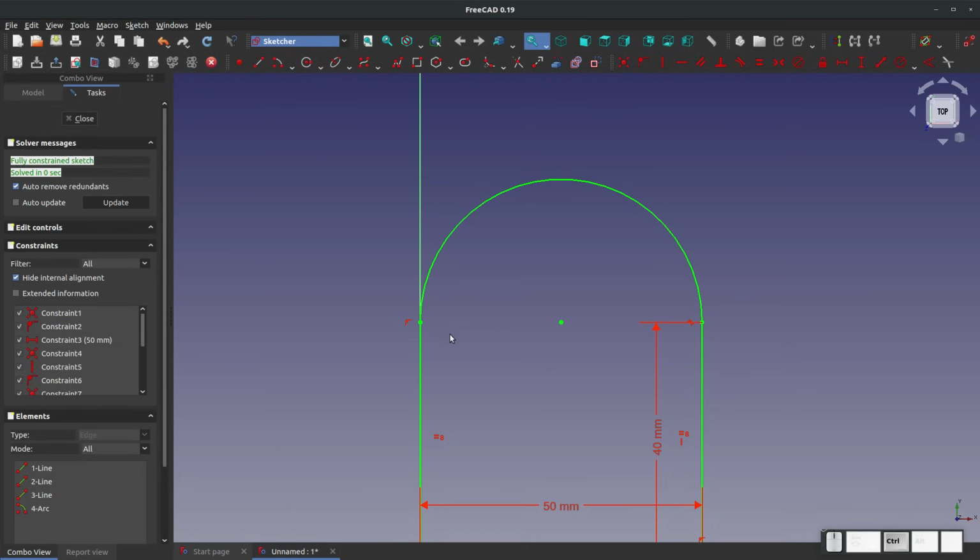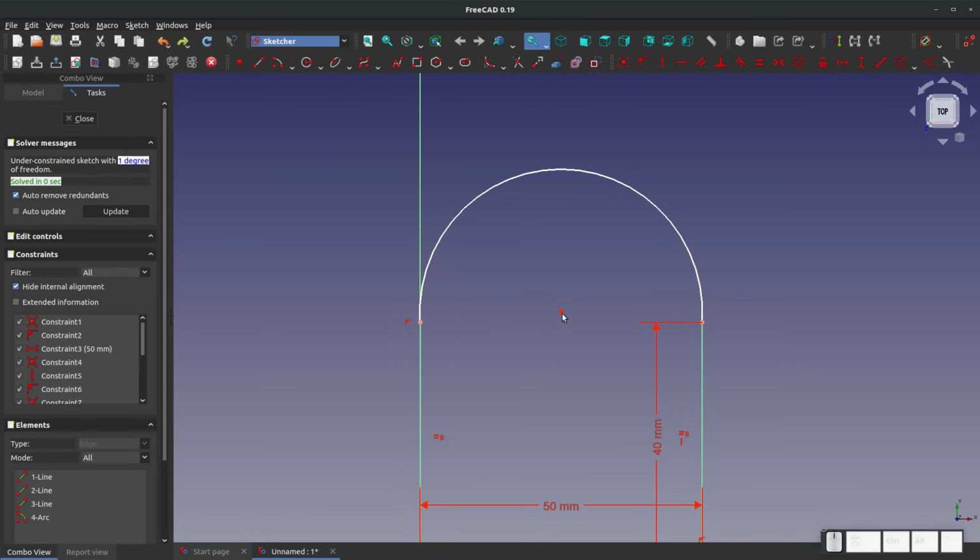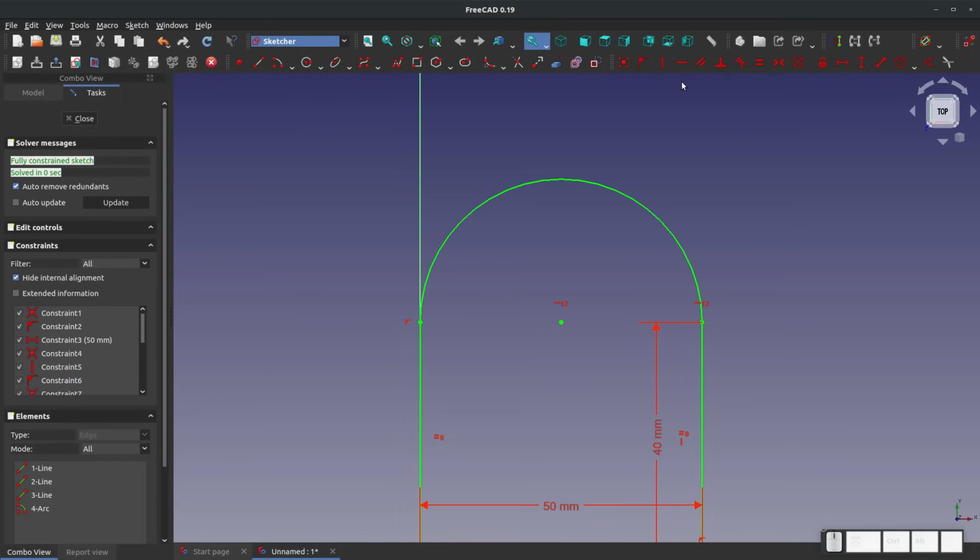What if I hit Control Z to undo the tangent constraint that I've just done? Another way of doing this is taking the center of my arc and this little endpoint of my arc and setting them to be horizontal with that horizontal tool. Now this point and this point are set to be horizontal, and you have that same smooth transition, because that's just the basic way that geometry works. It's the same thing as putting a tangent there.